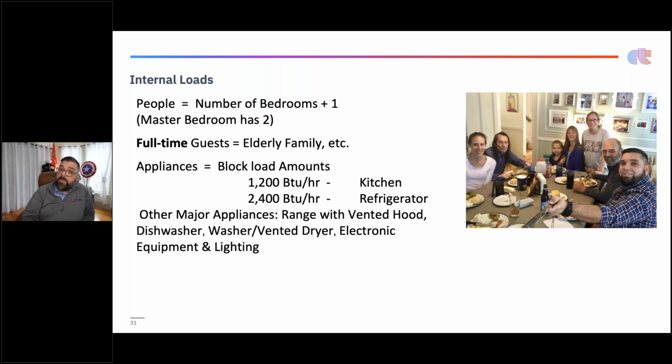If you're doing a room by room, you would add scenario number 1 to your kitchen, but then you actually have to take a look at everything else in the house, like range or washer and dryer, and what sometimes is an entertainment room, what you would normally call a living room, right? So all these other major appliances typically can be accounted for in scenario number 2. It's your kitchen plus those things. And it's for normal usage, right?